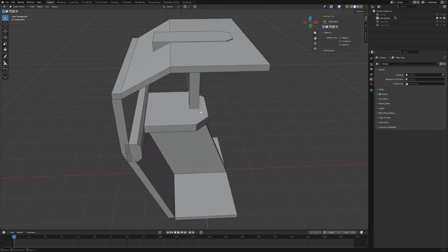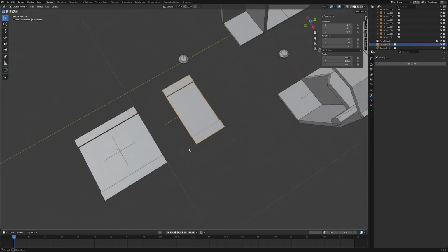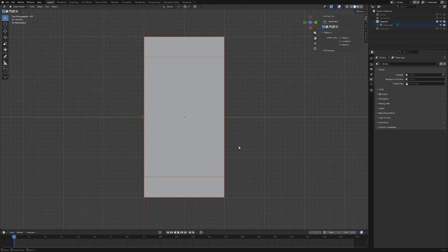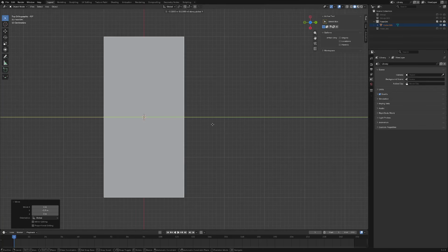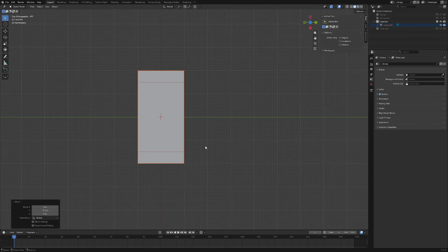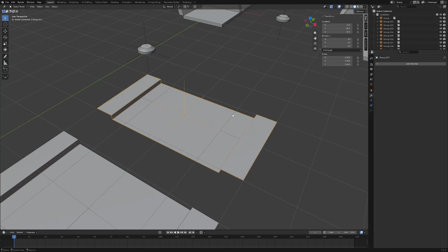So for example, in, out, and that's the group system, right? That's pretty much what it's going to be doing. Want that centered up for this particular one. You don't necessarily have to do that. You could actually put it in a corner or something like that as well. As long as you don't change it later on, you should be good. Sometimes you'll spiral out of control. Just hit tilde key, view selected, and tilde key is squiggly line at the top left.